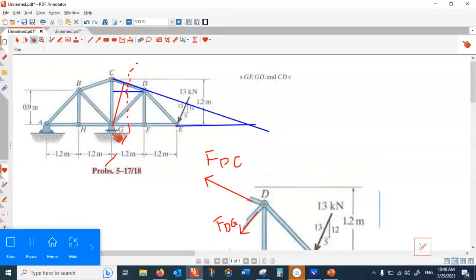the point of rotation. So I think that's very similar to what we had in the slide Monday or yesterday. Except over there, E was a support. You had to find the reaction at E. But here, because E has an input, I don't even bother to find the reaction forces. Just that single free body diagram is enough to find all the answers. This strategy is very important when you're solving a problem. If you get the wrong strategy, the chances are you're doing too much job, and with too much calculation, the chances to make a mistake.